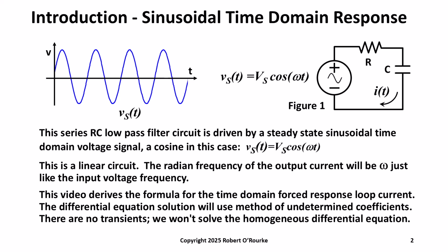Here in this video, we are deriving the current response. We only need to solve for the particular solution of the non-homogeneous differential equation. We don't need to solve the homogeneous or complementary equation corresponding to transient response.